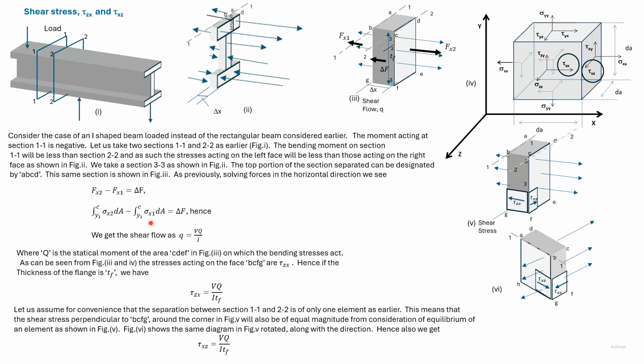We can write these stresses in terms of moment, and we can use the relationship between moment and shear force to give the shear flow as VQ divided by I. This process has been carried out earlier. Here Q, the statical moment of area, is of CDEF.